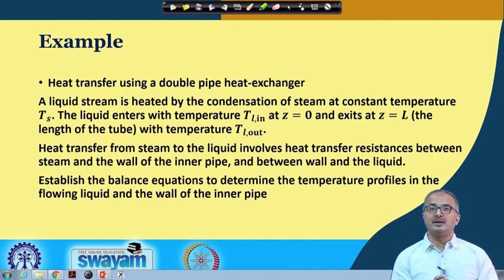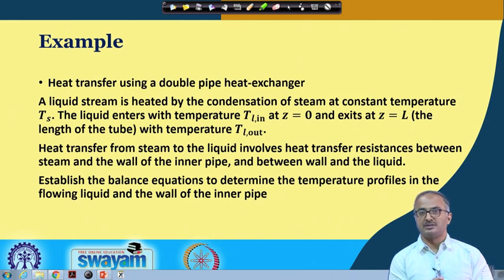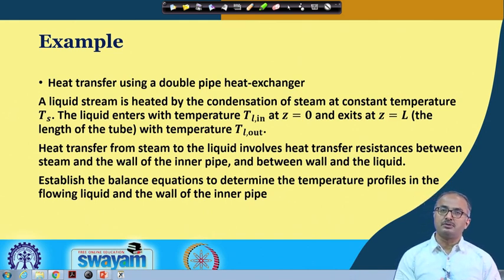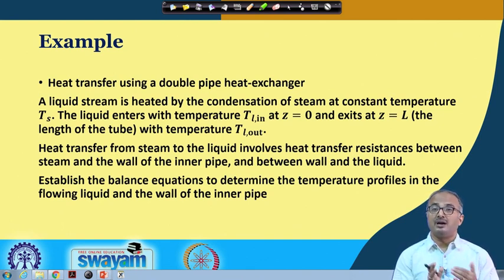However, you will find that generally for some finite or reasonable temperature difference, the contribution of the latent heat of vaporization is generally much more than the sensible heat contribution, and that is why we many a times neglect the contribution of the sensible heat in comparison with the latent heat of vaporization, unless otherwise we have a very large delta T. Okay?